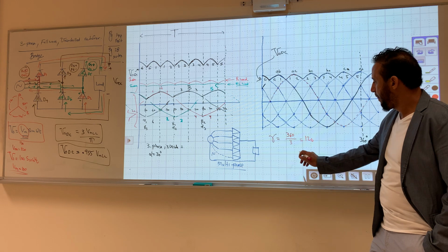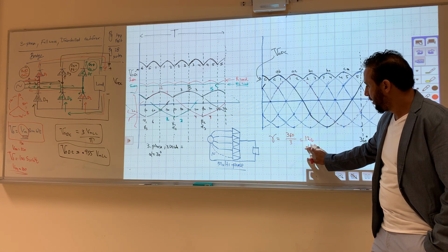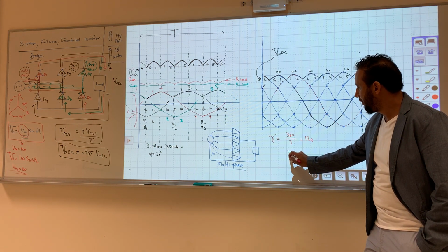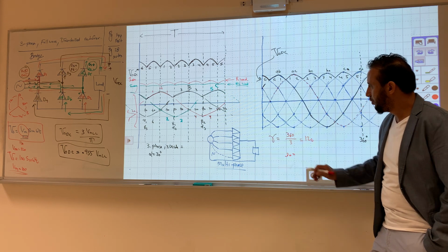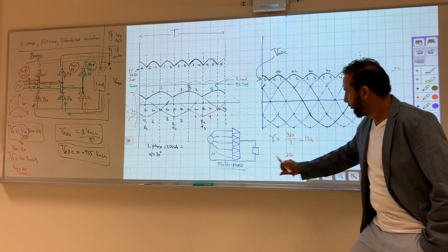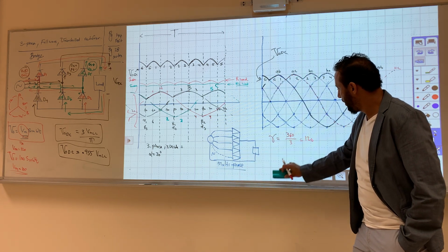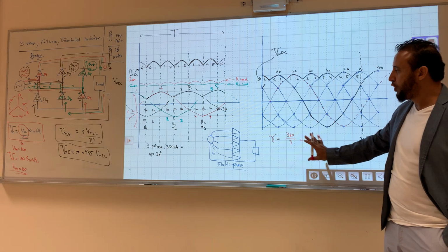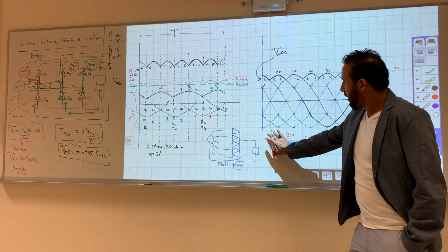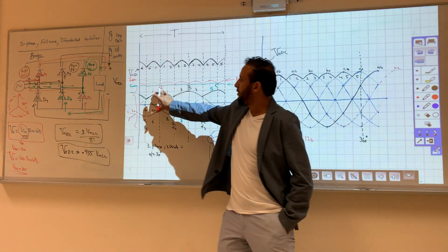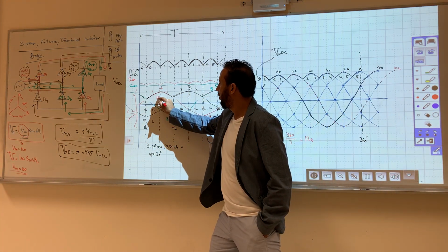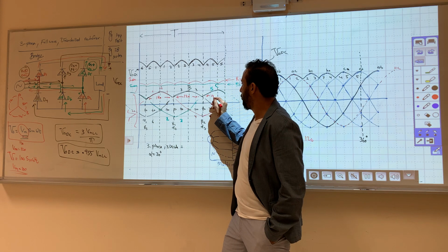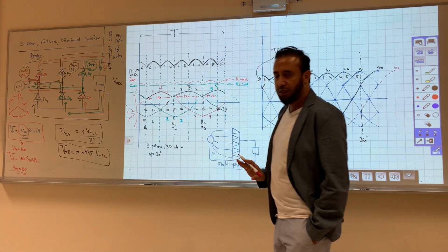Okay, so this is 120 compared to 30. We know that conduction angle here for the 3-phase half wave is 120 here and 120 here, and we know that the alpha is 30, so those are fixed.